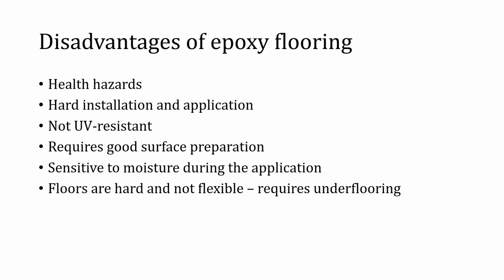Second, when the epoxy coating is exposed to UV light, either directly or indirectly, it causes noticeable and permanent damage as a result of photodegradation, including loss of gloss, ambering, for example, turning to yellow, and for the colored ones, chalking and breaking of the coating may also result.